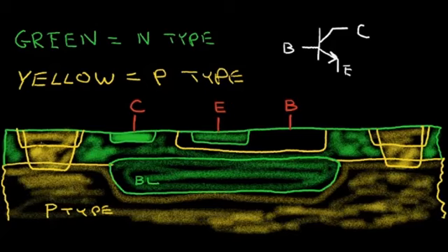So one thing to observe is that we have a PN diode. For example, here we have a diode. I'll draw the diode symbol. So we have a P material, we have an N material. Now this isolation region over here also forms a diode. So we have a diode, P material, N material. This buried layer, it forms a diode.